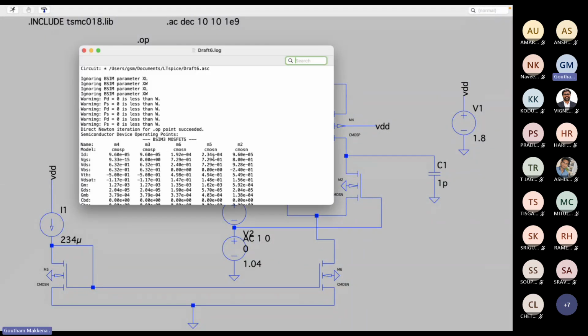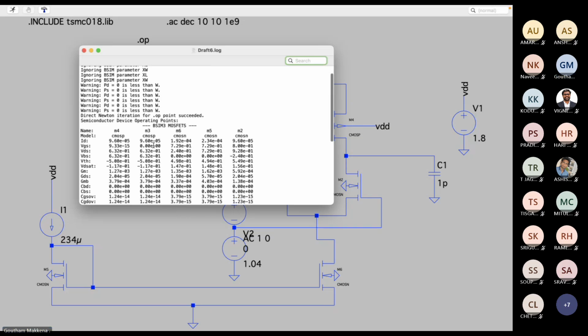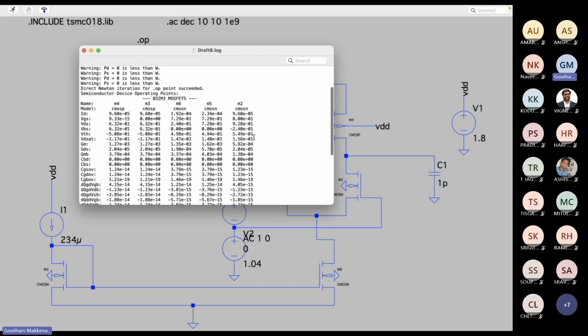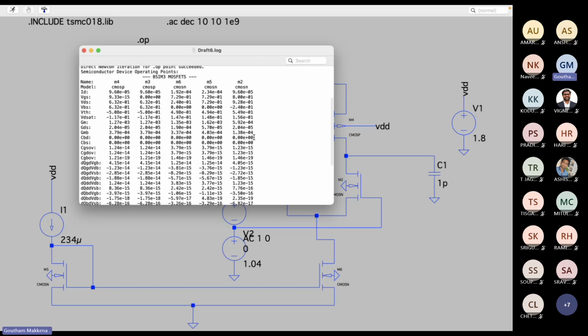View spice error log. Okay. Yeah, so this is much better, right? 96 microamps. So previously it was 91 microamps. Okay. And then if you look at the GM, it also increased. It was going to the ideal value. So we got 628 microsiemens. We are almost there, 592 microsiemens over here. So it is a better design compared to the other one. Okay, the previous values, of course.